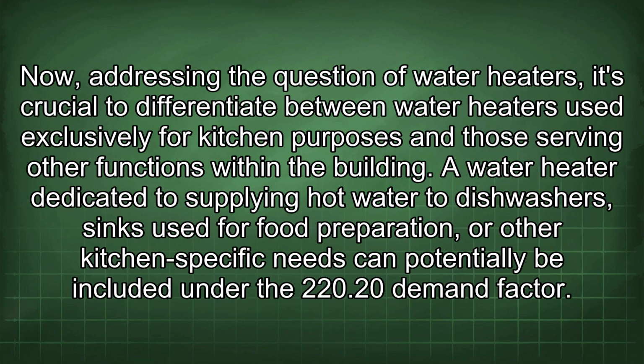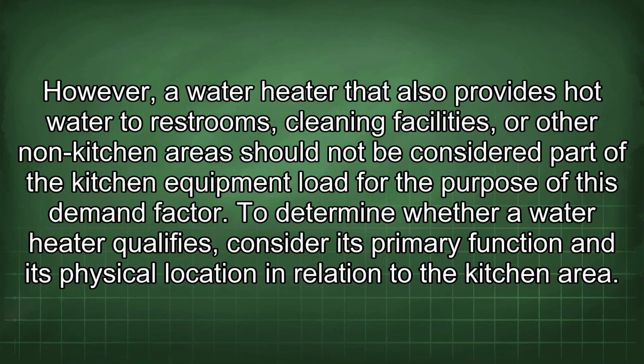Now, addressing the question of water heaters, it's crucial to differentiate between water heaters used exclusively for kitchen purposes and those serving other functions within the building. A water heater dedicated to supplying hot water to dishwashers, sinks used for food preparation, or other kitchen-specific needs can potentially be included under the 220.20 demand factor. However, a water heater that also provides hot water to restrooms, cleaning facilities, or other non-kitchen areas should not be considered part of the kitchen equipment load for the purpose of this demand factor.